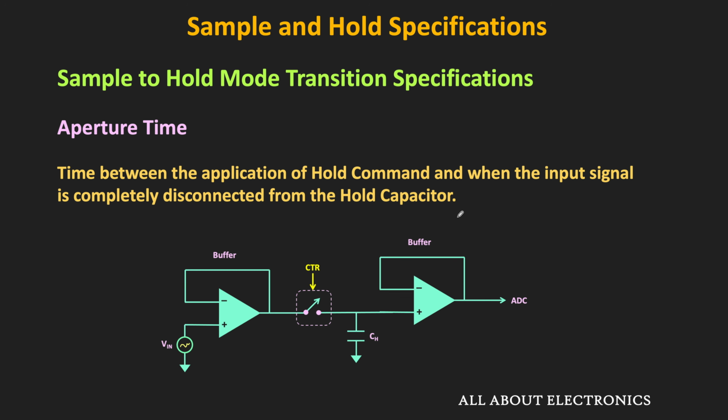So ideally, when we apply the hold command, then immediately this switch should get open and this input signal should get disconnected from the hold capacitor. But in reality, this switch takes some finite time for the opening. So this duration is referred to as the aperture time.